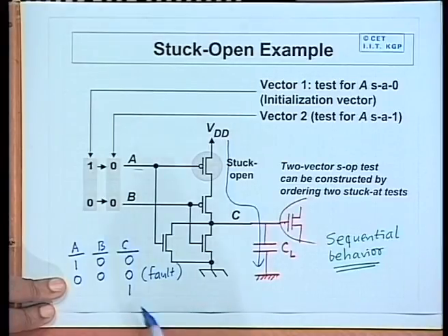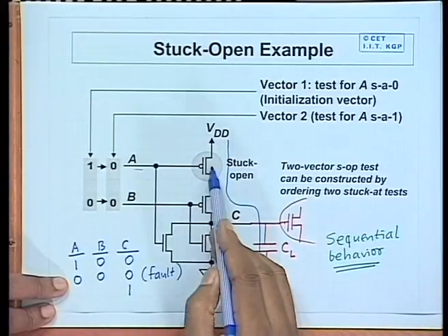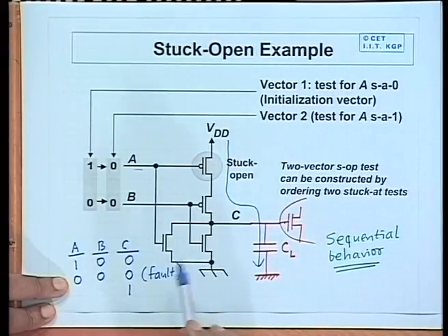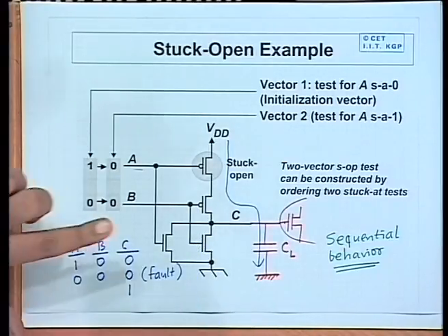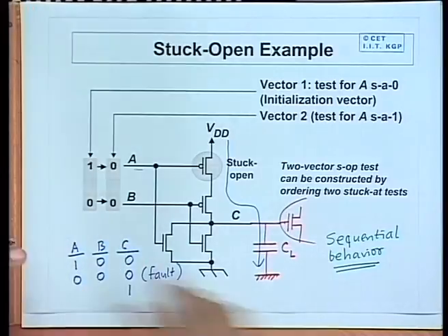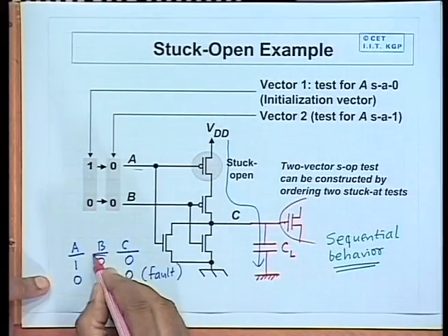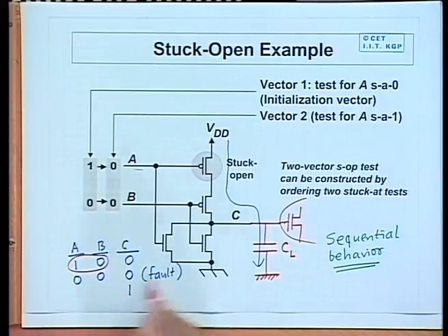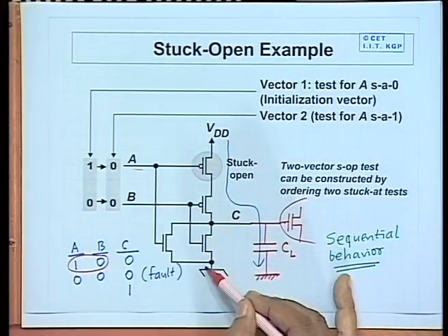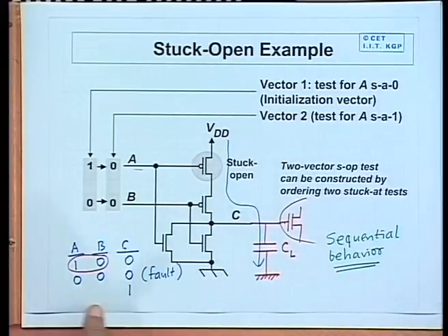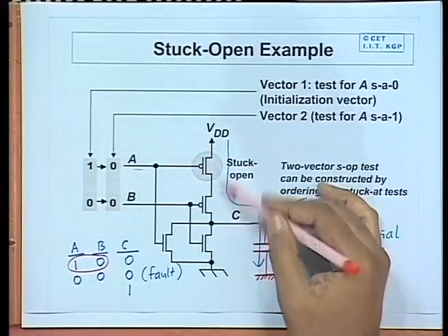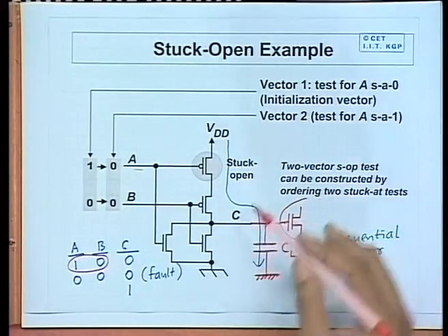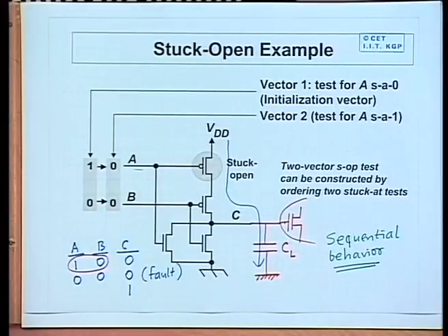Okay. So, here we can distinguish whether this fault is present or absent, but try to think: if I had not applied the previous test vector, could I detect this fault? Because the previous test vector was applied with the sole intention of discharging the capacitor to a known state. But if I simply apply 0 0, which means the output is open, what will be the output value I do not know; that depends on whatever was there previously.